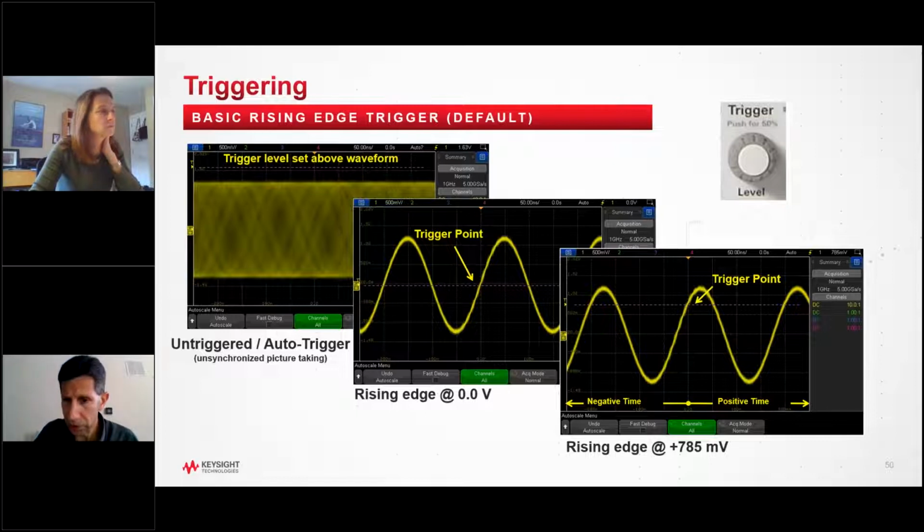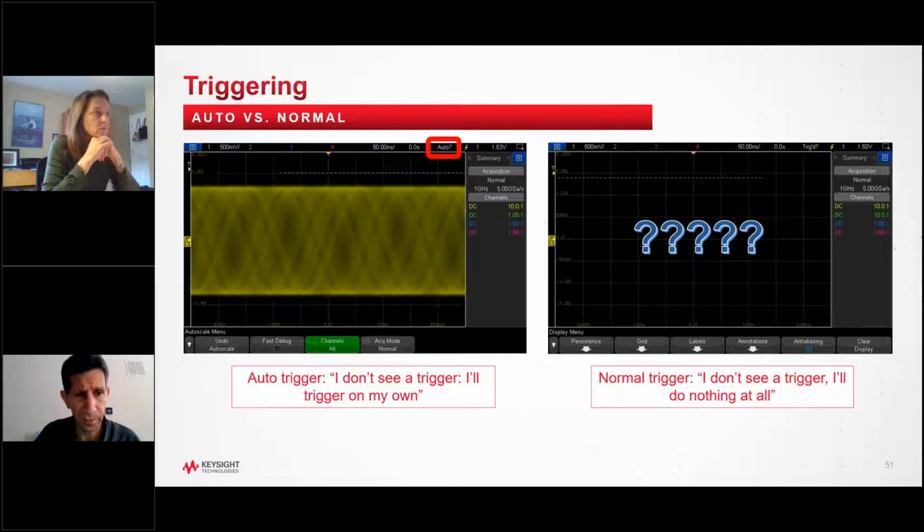And again, you can control that in the menu of the oscilloscope. You also see trigger control, 50%. That's the most commonly used trigger, where we're triggering right in the center of the waveform. So we have a quick way. When you hit that button, it goes out and takes a snapshot of the signal, and then sets the trigger level right in the middle, assuming it's not a single shot signal.